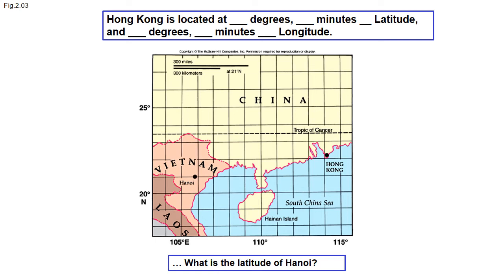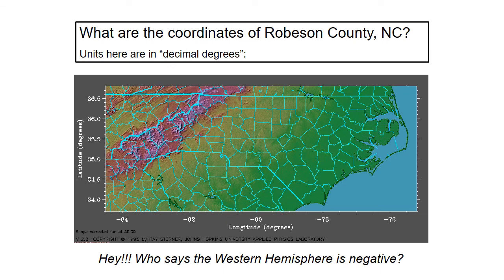And here's an extra question in there. This one's directly from the book. Sometimes on some websites and some devices, they don't give the latitude and longitude location in degrees, minutes, and seconds. Sometimes they use a decimal of a degree. For example, you may have a latitudinal position of 35.5. Well, what does that mean? 35.5, so it's 35 and a half. That would be 35 degrees, 30 minutes then.